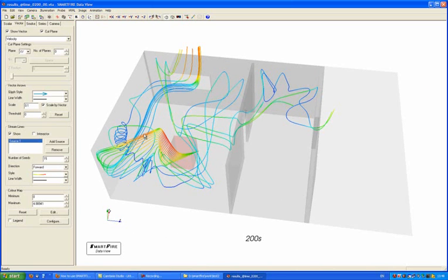They rotate into ceiling jets, and then the complicated nature of the recirculating flow in the back of the room is demonstrated with some of the particles heading out through the window and some of the particles recirculating around and then heading out through the spill plume into the outer room and then out into the extended region.